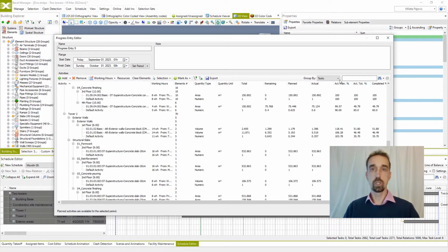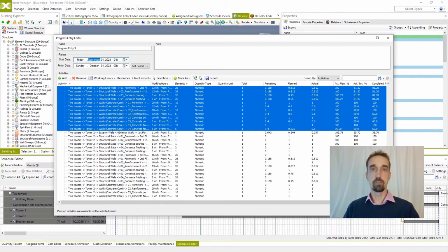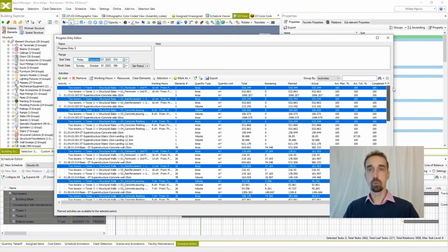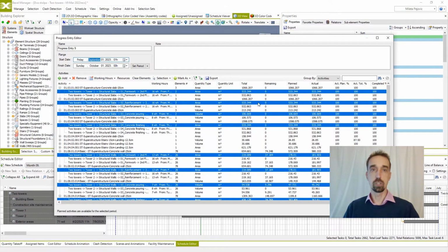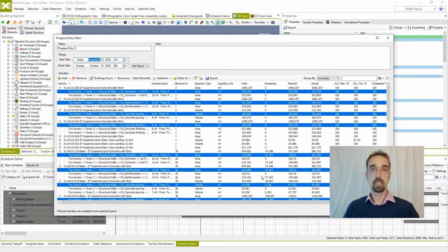And after consultation with on-site supervisors, these values can be approved or they can be changed before final approval of finally executed works. Also, if project managers have information from contractors or subcontractors about the resources used for the execution of each activity or each task, this information can also be populated and adjusted according to real use on site. And by changing resource quantities, the system will recalculate actual cost and all respective information and performance indicators such as, for example, earned value, cost variance, cost and schedule performance index, and similar.